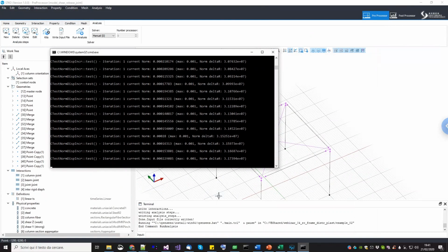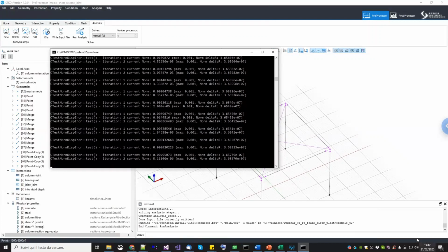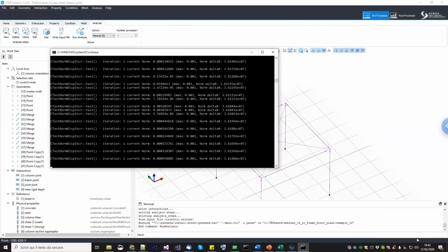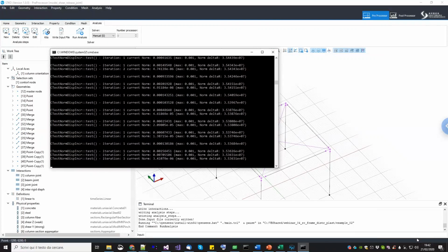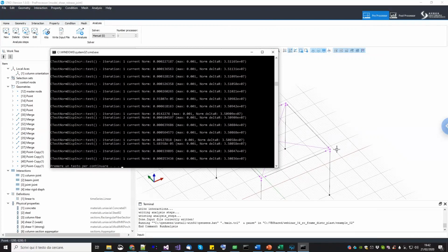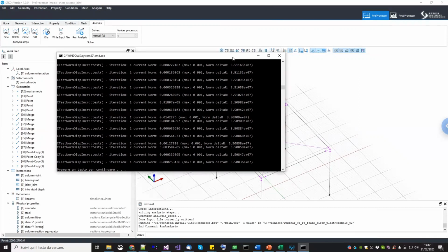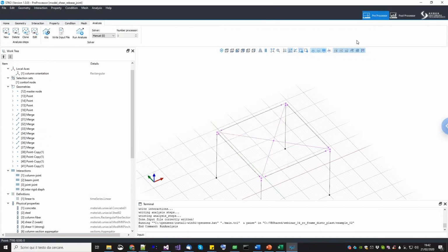Now, as you can see, creating the beam column joints by hand is quite tedious. It takes a lot of time. It took almost 20 minutes. And that's why we are working on a simple procedure that lets you select only the vertices, and STKO will generate the beam column joints automatically. Now, it was not ready for today, so we will show you this new feature in the next webinar, which will be on the concentrated plasticity approach.